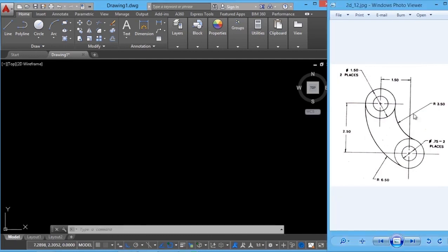We are going to apply the concept of layers in this figure. You have 2 options to do that. You can create the entire figure first, then create the layers and transfer individual objects to individual layers. The next option is to create a layer, keep that as the current layer, then make an object in it, and repeat the same for the rest of the objects, which will take relatively more time. So I'll create this entire figure, then I'll transfer individual objects into individual layers.